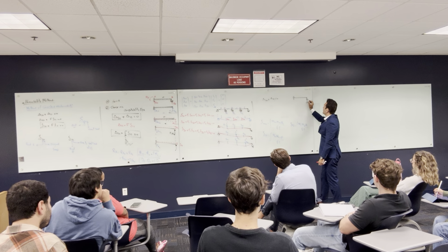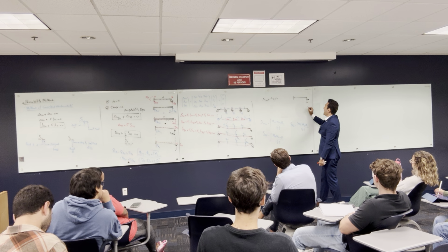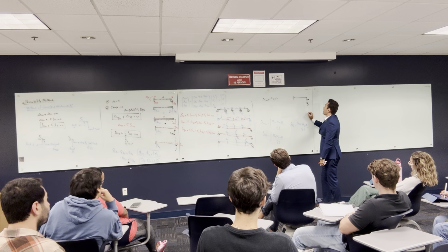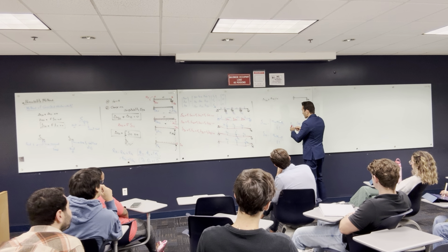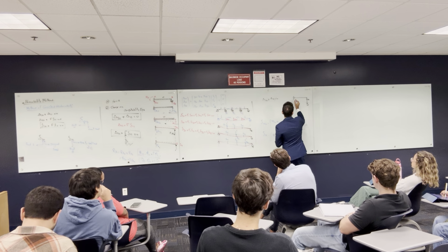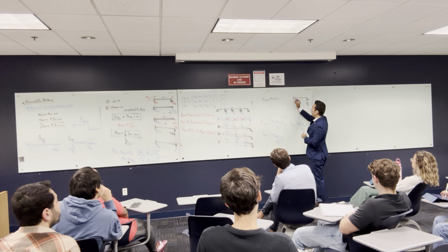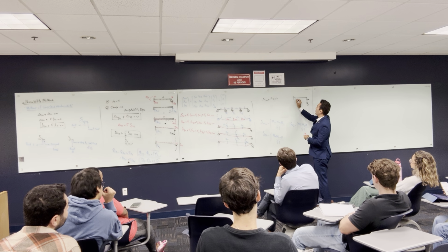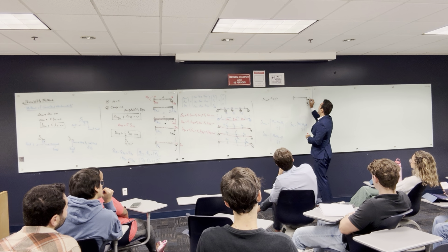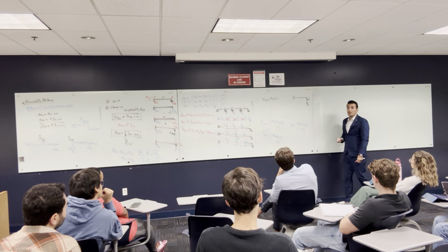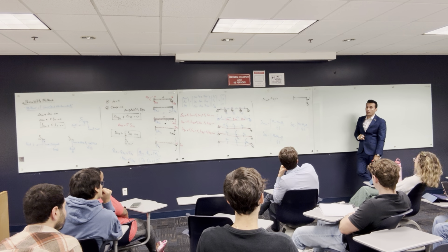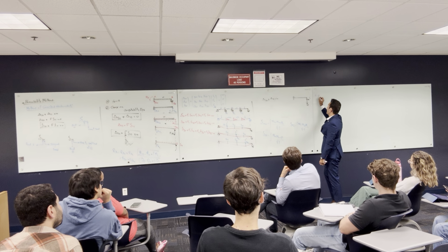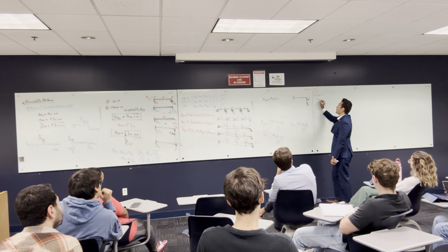So if I told you that this spring is gonna have K and we need to find the value of F, can you tell me how much deformation you're gonna have here? Here, like before, 0. Here, this is a spring, so you are gonna have a deformation, something like this. Delta. So can you tell me what is the value of this deformation? F equals delta K, so F is equal what? Delta K. Exactly. And then delta is equal to F over K.